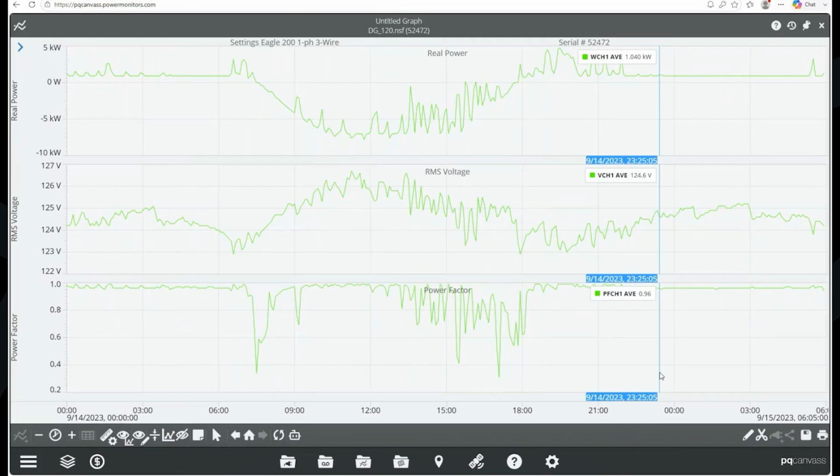A substation monitor tells you whether the feeder exports, not where it starts. A service or transformer monitor catches localized export earlier. One at a regulator or capacitor bank tells you whether export is affecting voltage control equipment.